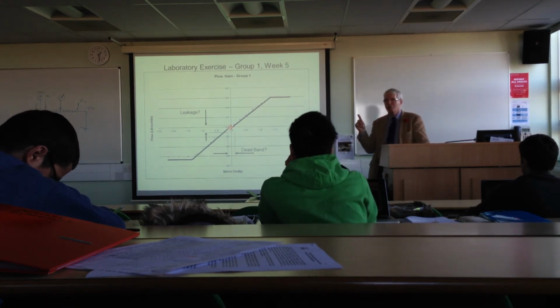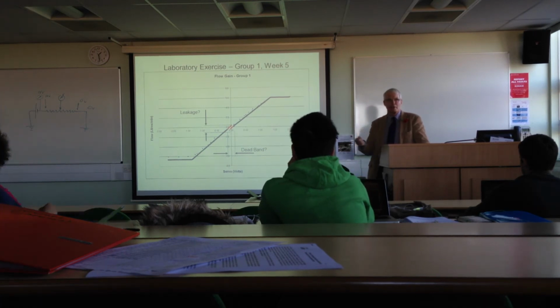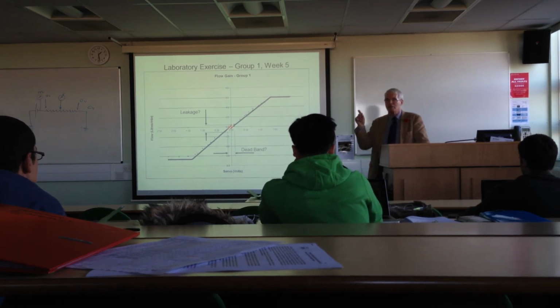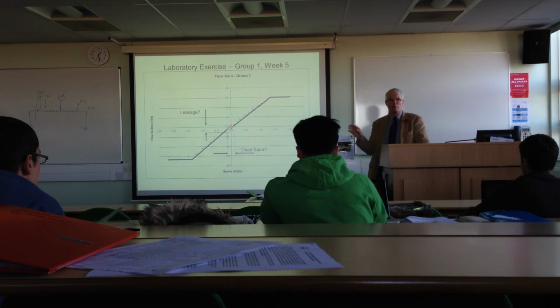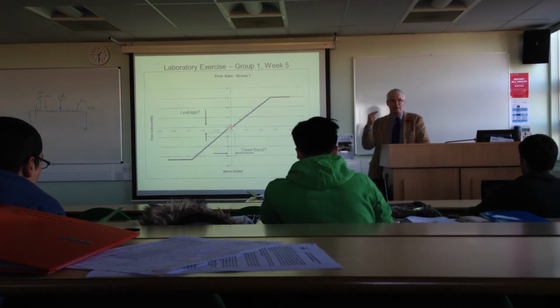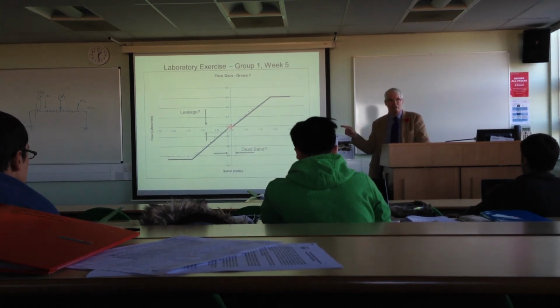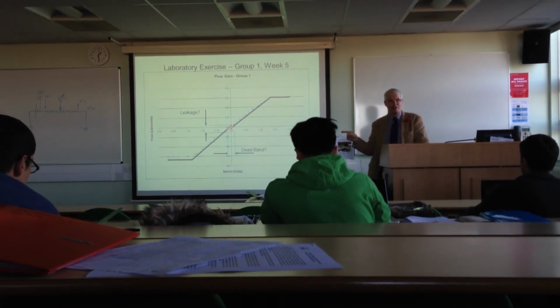I think I told you that the hydraulic motor has got a little drain coming from it. The circuit diagram hopefully should show that. Because we don't want any leakage inside the motor to actually blow the shaft seal out. So we just bring it back to the reservoir. So it means because those little pistons, and it is a piston motor we've got, don't have any rubber seals on them, a little bit of oil can actually get past those. A little bit of oil is actually used by the slippers, I'll talk about those in a little while, to actually make them float like little hovercraft. So some of the oil that goes into the motor actually leaks and it doesn't turn.